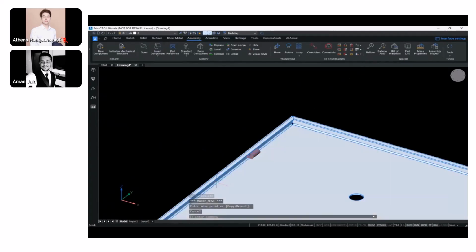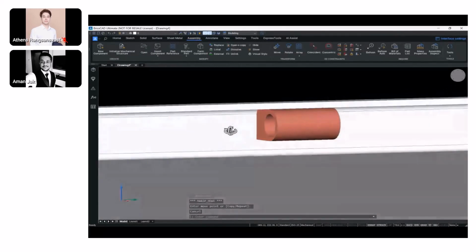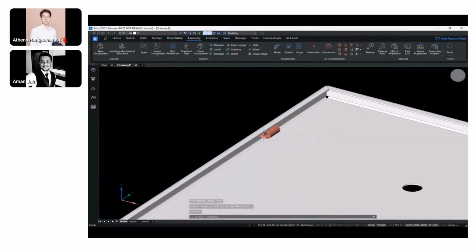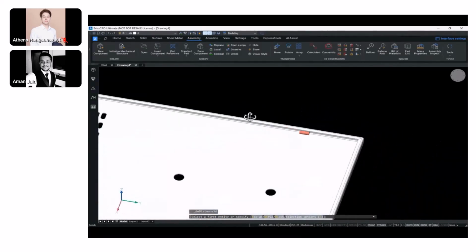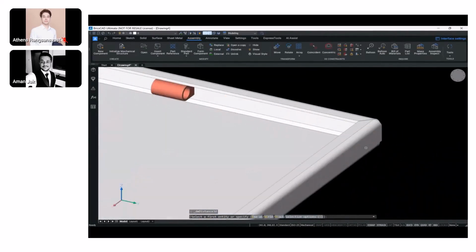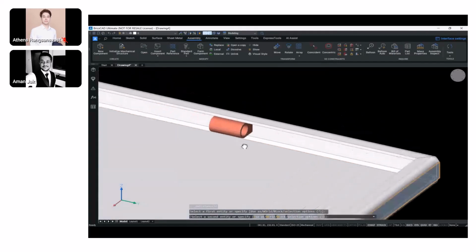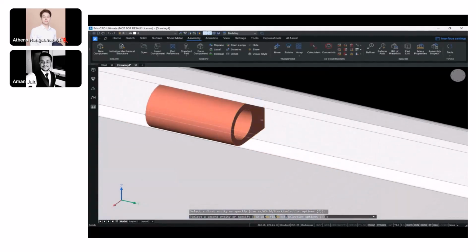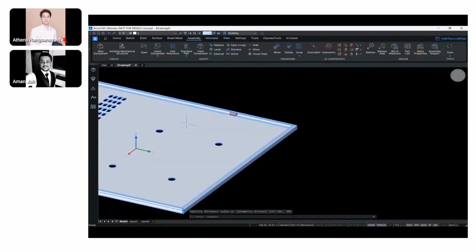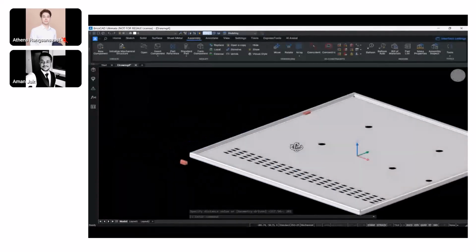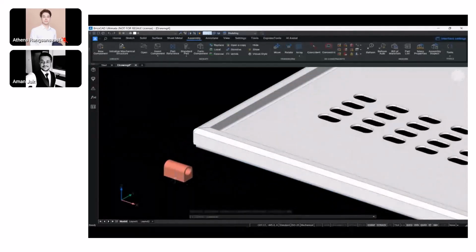Right. So I can just move it across, and now it's freely movable across the y-axis. And what I can do is now give it a distance constraint from the outside side of the door to the flank or to the hinge at a distance of 200 or 201, because we need some clearance when it'll get mated with the hinges present on the body.